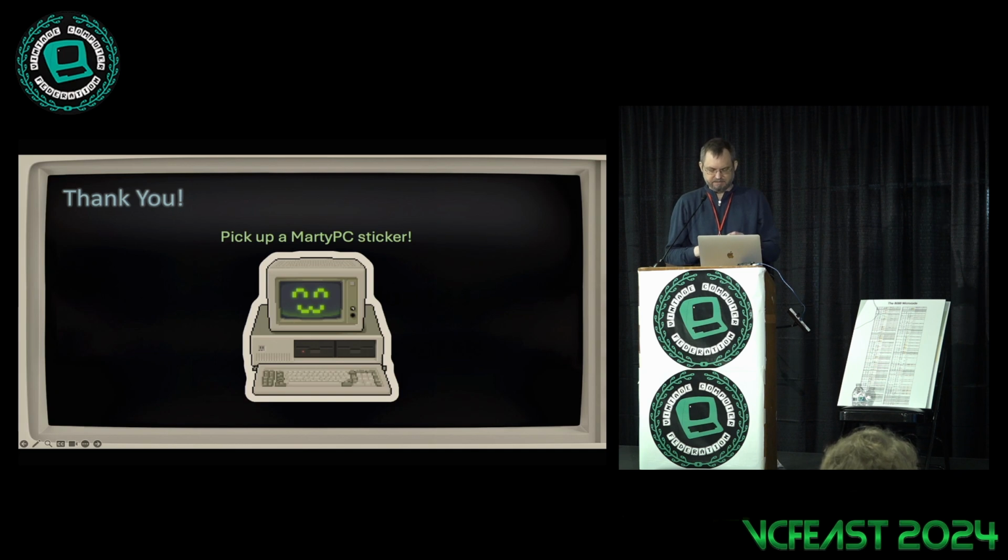I have a Harris CMOS version that's what I used to generate the test set. There are slight flag differences between the two. There's also lots of little differences, like the Harris will delay interrupt by 1 instruction after a push of a segment register, which is a little excessive, because pushing a segment register doesn't affect the segment register, so why would you do that? Nobody knows. You'd have to ask Harris.